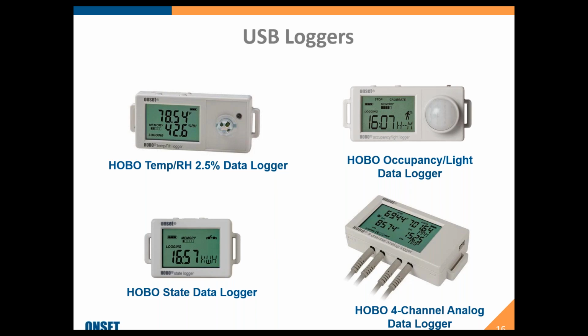And then our Hobo 4 channel, which in the HVAC or facility space is probably the most common logger for troubleshooting. You're able to put in multiple probes, so multiple external temperature probes for maybe your supply, return, and mixed air, and we'll throw in some amperage there to get some power. That logger will fit that.